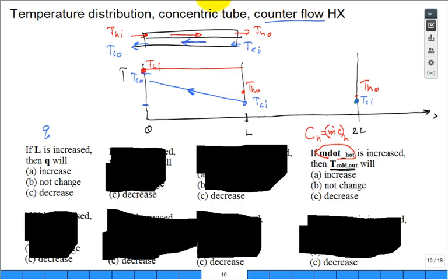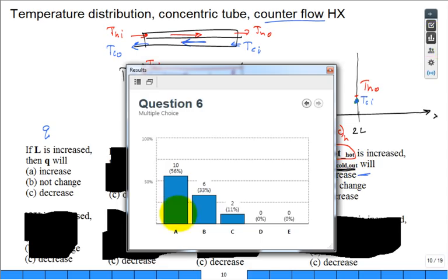And what's driving the heat transfer? It's this theta. A large theta over the entire heat exchanger drives the heat transfer. So what's going to happen, it's going to change the shape of this cold line. It's going to be more like that, isn't it? It'll be more like I've shown. So what happens to the cold outlet? Doesn't it increase? I didn't say these were easier.